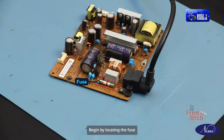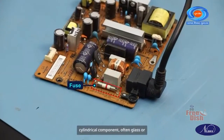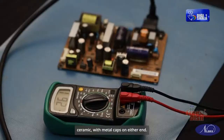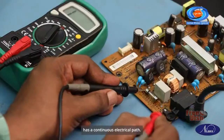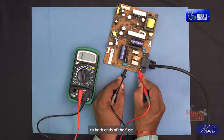Begin by locating the fuse on the power supply board. It is typically a small cylindrical component, often glass or ceramic, with metal caps on either end. To test the fuse, we will use a multimeter set to continuity mode. This setting helps determine if the fuse has a continuous electrical path. Attach the multimeter's probes to both ends of the fuse.